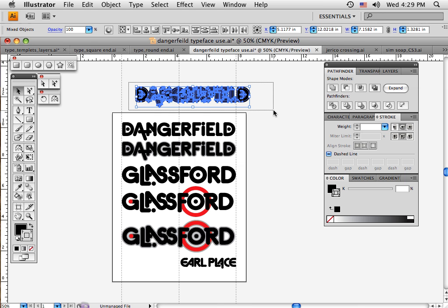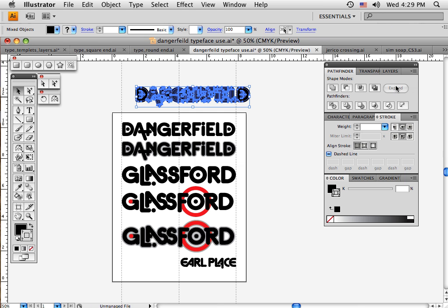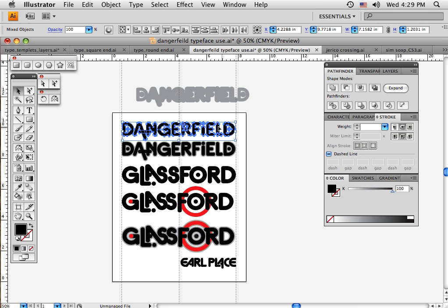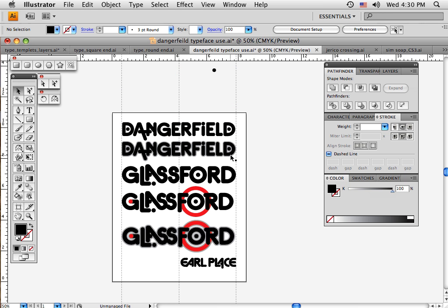If I take this all together and melt them, Option key and the melt key, then they go down to just a solid fill. There's no stroke anymore. The stroke is melted into the fill, and that I can turn to a light gray, and then I can take the original letters and put them over the top, and I get the outline happening there. Okay, so that's where this outline comes in. That's around all the edges, inside and outside, around the circles.